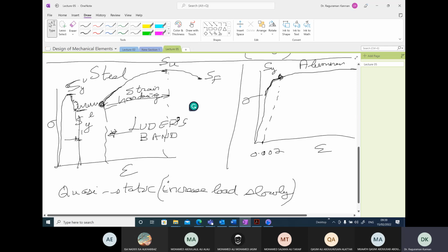At the point where the necking is, the area of cross section significantly decreases, and therefore it looks like the force is also decreasing, and because the externally applied load taken by the specimen is decreasing, the stress seems to decrease. Why? How do we calculate this stress? This stress is actually calculated as the force taken by the specimen, F, divided by the area of cross section.